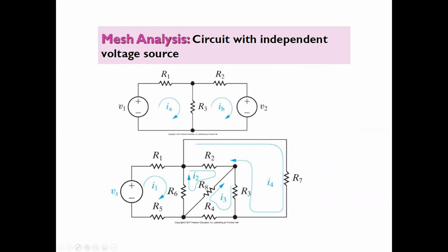Then from that, you can solve all the questions regarding this circuit. For example, if you want to find the voltage here, you can always write it. So this one, for example, is Vx. So what is Vx? Vx is actually your IA multiplied with R1. And for example, this one is also Vy. So Vy is equal to IB R2.